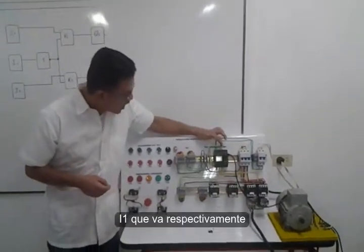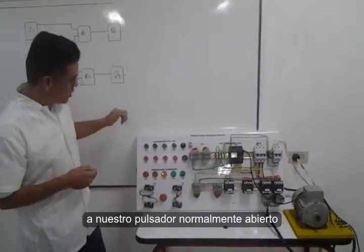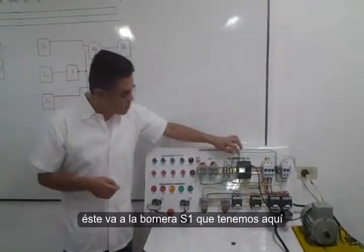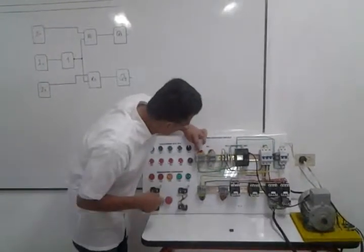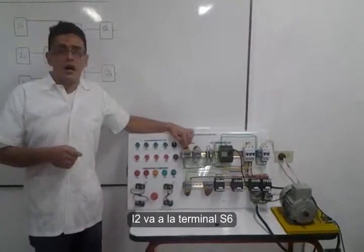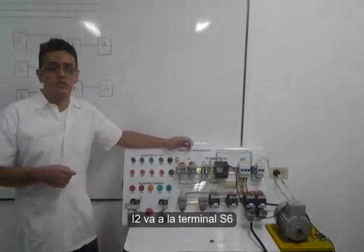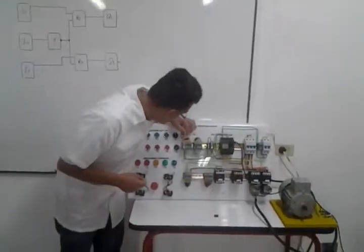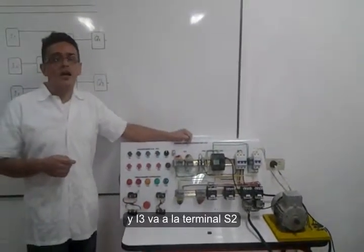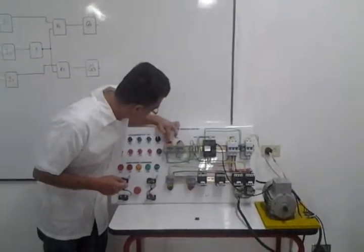The input I1 goes respectively to our normally open push button. It goes to the terminal S1 that we have here. S1, the first input goes to S1. I2, what is I2? I2 goes to the terminal S6. And I3 goes to the terminal S2.